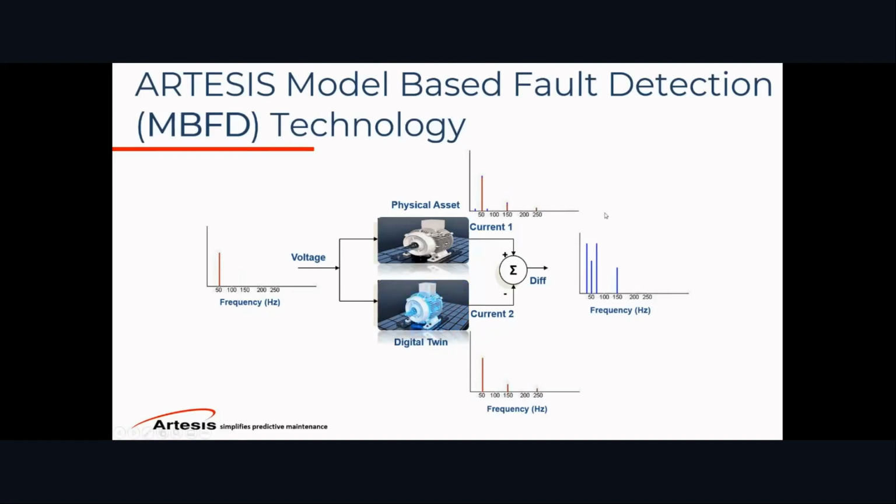Depending on those frequencies and the amplitudes, you will have residual current waveform distortions. Our voltage supply is the same, our learned model is here, and we are constantly taking the difference between the two. There are some additional frequencies, these distortions we are seeing here, so those must have come from mechanical changes in the motor behavior.